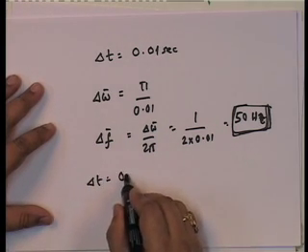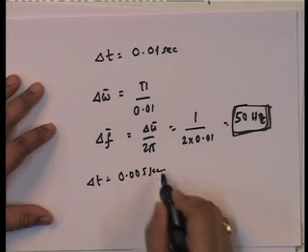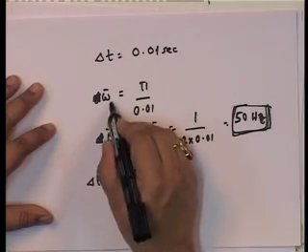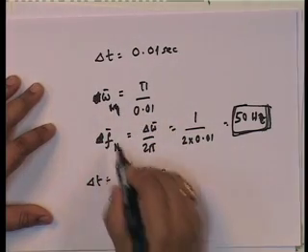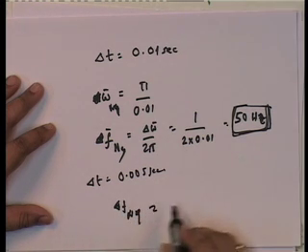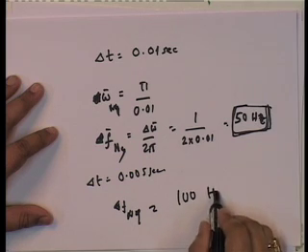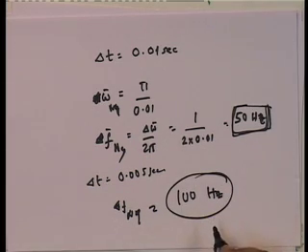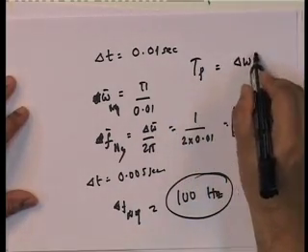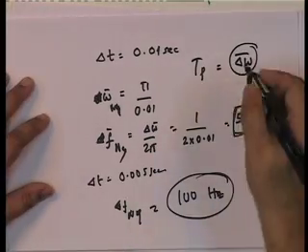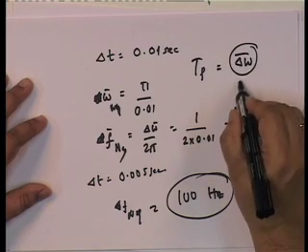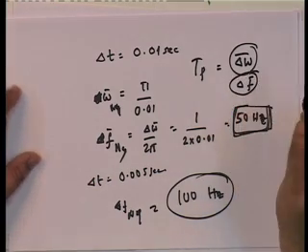For example, if you take delta t equal to 0.005 second, then this is not delta f, this is the Nyquist, f Nyquist. Then f Nyquist would be equal to 100 hertz. So, therefore, Tp determines delta omega bar. Although delta omega bar is circular frequency, I will represent it by f, because this is something that we know.